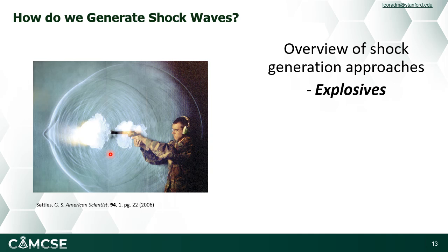Of course, this was a little bit destructive, so we since have been able to come up with slightly more controlled ways of studying shock compression. It's also worth mentioning that, especially in this type of geometry, these diverging versions of shock waves are actually decaying shocks, which impose slightly different conditions on the materials from the planar shocks that we discussed initially.